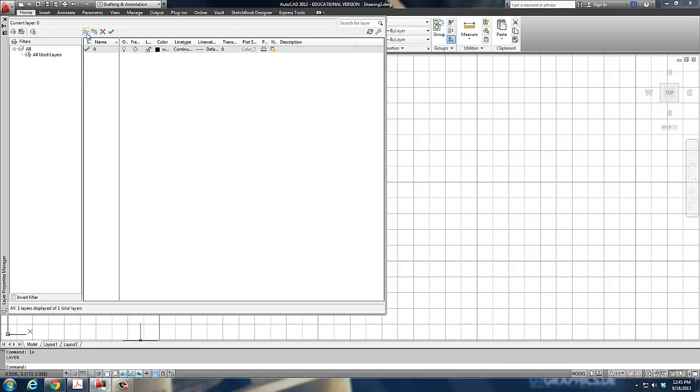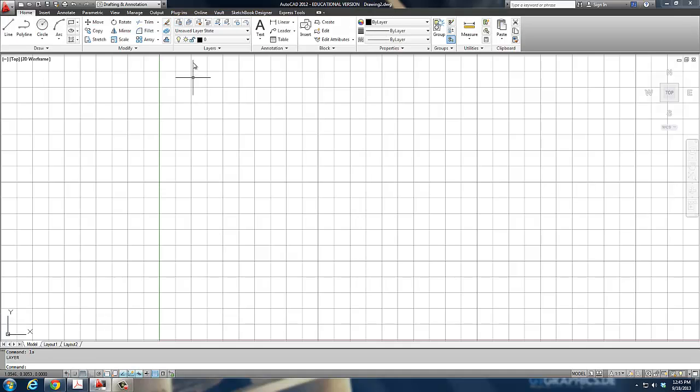And it's so much easier to work in this window than it used to be in the old one. I can add layers. I can freeze layers. I can delete layers. I can make a layer current. Well, all that stuff can also be done right here at our layer command bars. Okay? See, I can add layers, I can subtract layers, I can move layers up and down, freeze, thaw, etc. So it's really pretty easy to function in the program. It's quite intuitive compared to what it used to be. So as you're working, we try to keep things simple and straightforward.